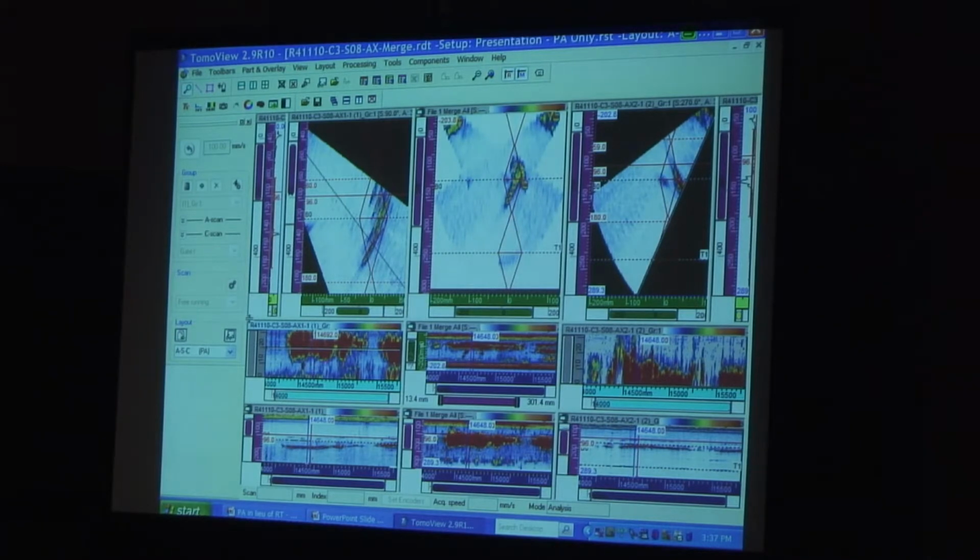So the technician has the capability of not only defining the length, start points. At the end of the day, we don't care what the maximum amplitude is here. We're dealing with a crack or we're dealing with a flaw. Really what we care about is the endpoints and the depth through wall location. All that's available in these kind of tools. They do have a reader version, or basically I call it TomoView Lite, if you will, that does give owner users and fabricators the ability to actually do some limited manipulation or view of data.